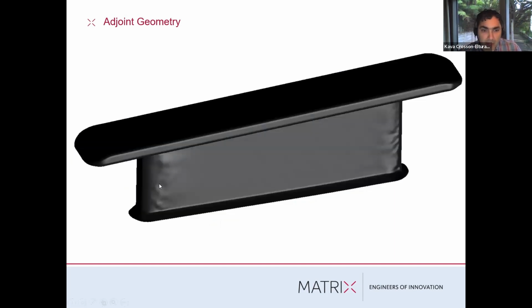Now the wrinkles on the side at the leading edge of the supporting column and the trailing edge of the supporting column are more substantial. So these bumps are on the order of 30 millimeters, either in or out. And quite interesting, it's quite irregular and organic, and somehow the adjoint solver has found these zones, which, by the way, are self-interacting. So all of these features interact to produce a holistic reduction in drag, something that's very difficult, if not impossible, to do with traditional optimization techniques like parameterization.